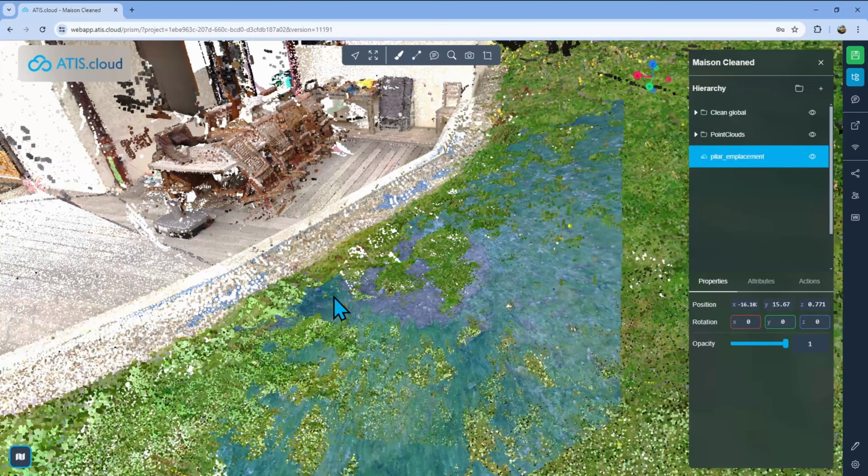Right, let's head over to the second project that we're actually going to work, and that's going to be installing solar panels. So there are a few things that we have to go through before we actually go ahead and install those. The first thing being the orientation of the sun, which is really important when you use solar panels. And so you want to have south and or west orientations. What I did is I added a compass so I can show you physically where the north is. So I have the north that is up there in my project, and then I have the south down there, west and east here. So basically I'll have to have panels that face south, so downwards compared to where I am right now, and west, so on the left.